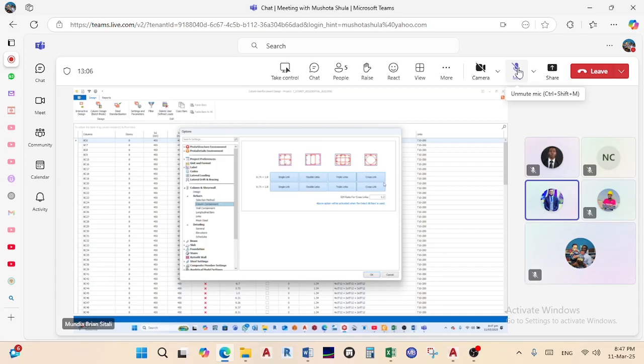But because I clicked everything here, I'm exposing the column design to be able to use all these 4 options of stirrup placement. That's just an example. It's the same thing I did even on the wall containment. Instead of this point where it's just using one link around and then ties, I clicked this one which has end zones. So it's not really that I was restricting it. I was just giving it a preference, what I prefer the reinforcement to be laid out like.